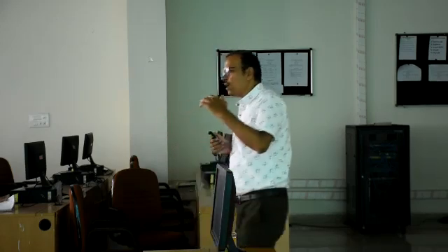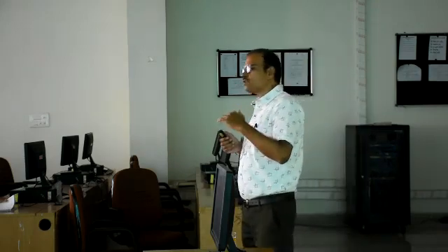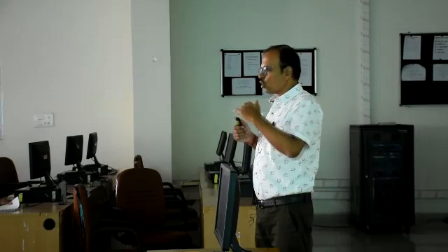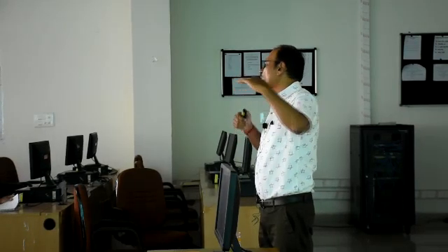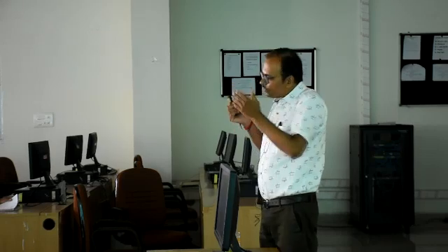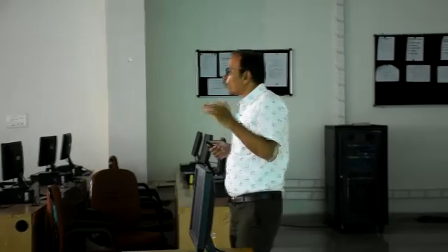And we will dispatch this wind power based on this forecast to the grid, and we will manage the control of the charging station, battery storage systems, in such a way that will absorb the power when the instantaneous power is greater than your average power, and we will release the power when instantaneous power is less than the forecasted power. Okay. This may be one of the strategies.